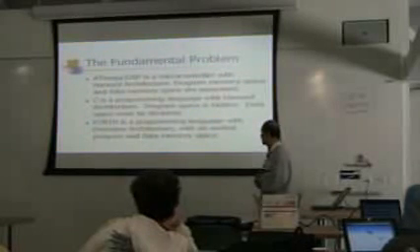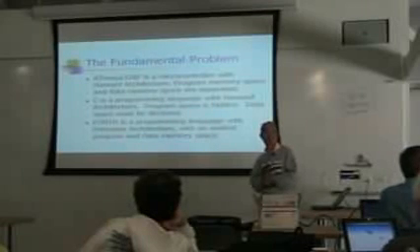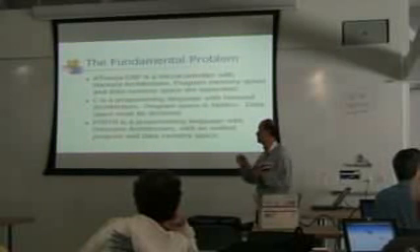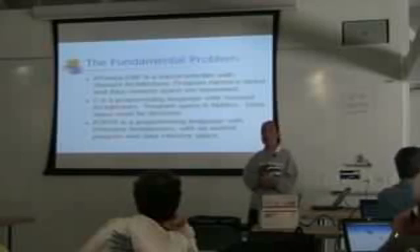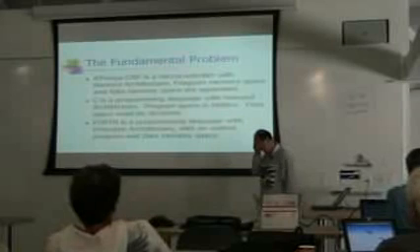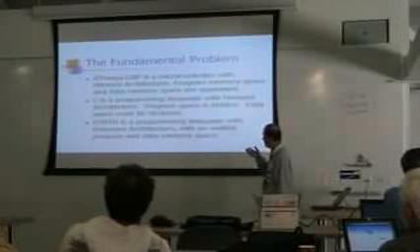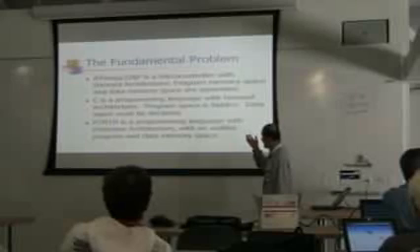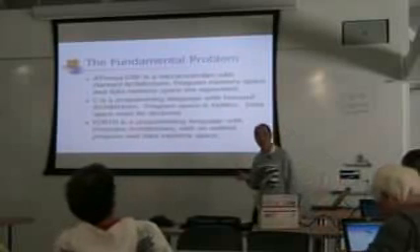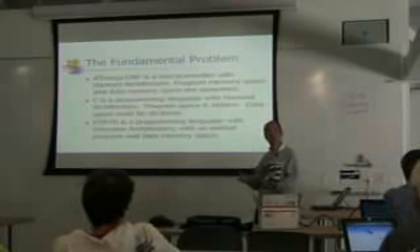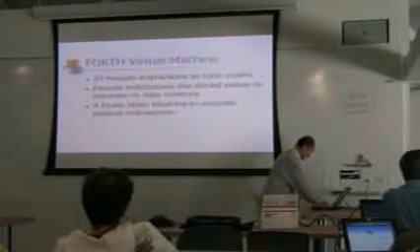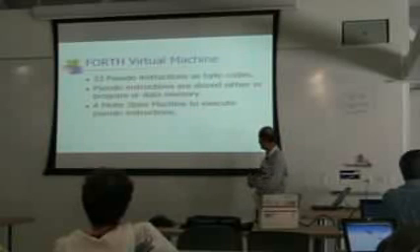But eForth is basically a Princeton architecture. It doesn't care where things are stored. You can store anything, read anything, write anything, execute anything. And that's the basic architecture of eForth. So what we want to do is use a Harvard architecture microprocessor and a Harvard architecture programming language and really do a Princeton architecture system. And this is how you can do it.